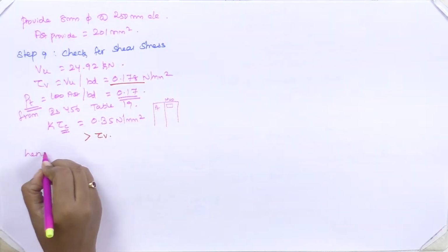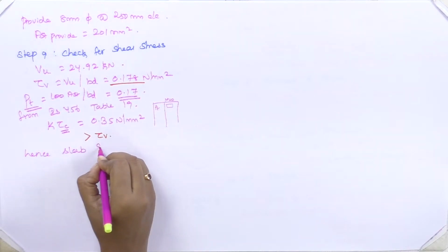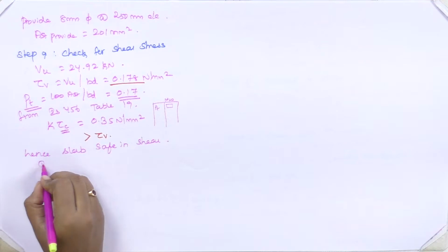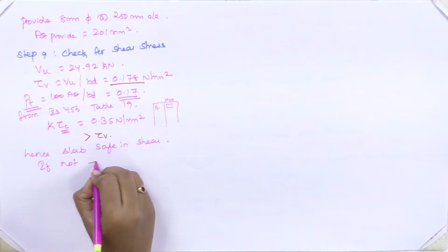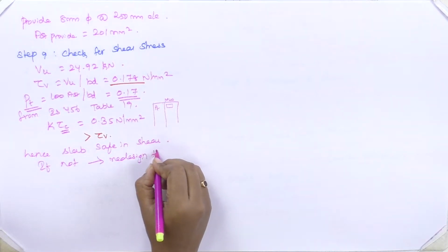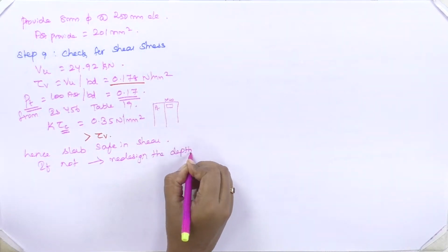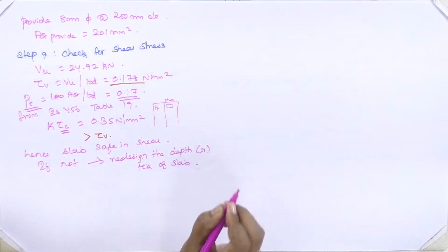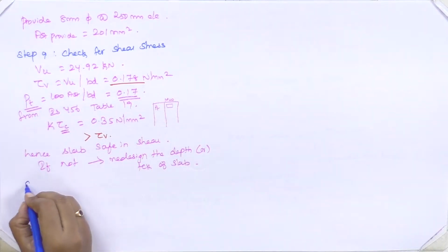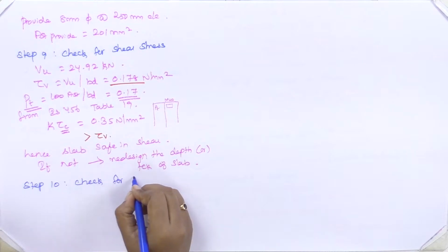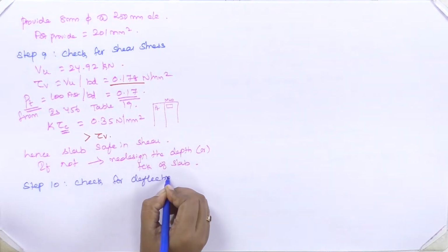Hence the slab is safe in shear. If not, redesign the depth or thickness of the slab. Okay, then step 10, I'll do some check for deflection control.